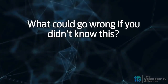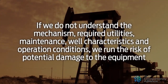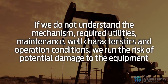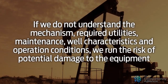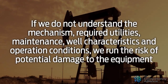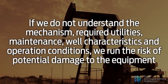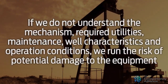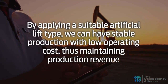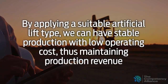What could go wrong if you didn't know this? What could go right if you do know this? If we do not understand the mechanism, required utilities and maintenance, and well characteristics and operation conditions in our well or process, then we run the risk of potential damage to the main equipment and downtime. Production will go down, and we may be at risk of having an extended shut-in to try to repair or replace the equipment. On the other hand, by applying a suitable artificial lift type for our well, we can have stable production with low operating cost, thus maintaining production revenue.